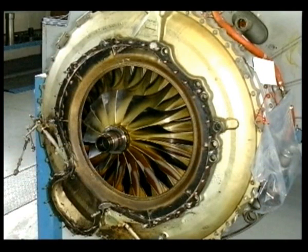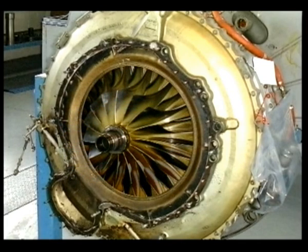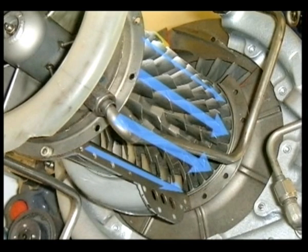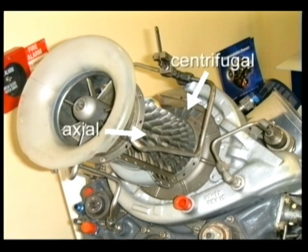In the centrifugal compressor, air enters the impeller at the hub, then flows outward through the impeller vanes. This type of compressor is commonly used on most modern turboprop or turboshaft engines of under 1,000 horsepower. They are cheap, lightweight, compact, and can ingest dirt without suffering damage. Axial flow type compressors are better suited to high mass flow, where the air flows parallel to the compressor shaft. Some engine designs incorporate both types of compressors, where an axial flow compressor feeds a centrifugal compressor.